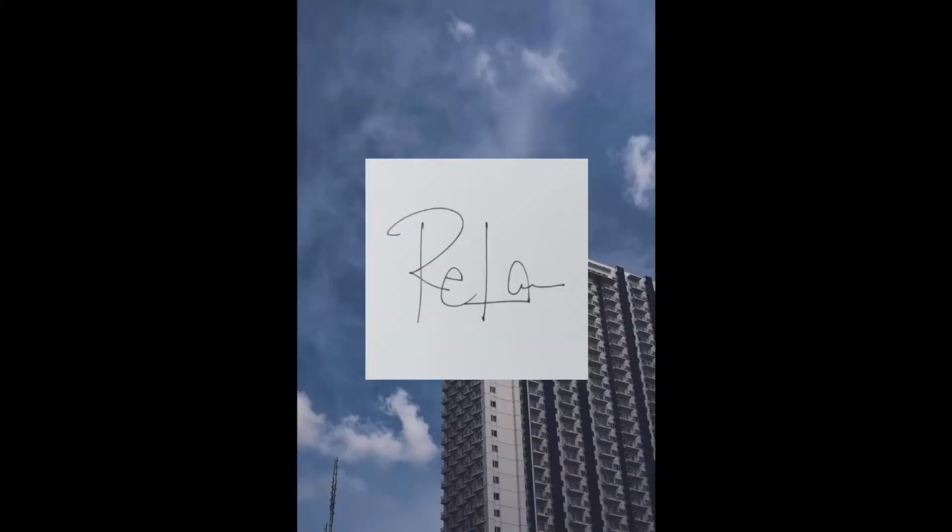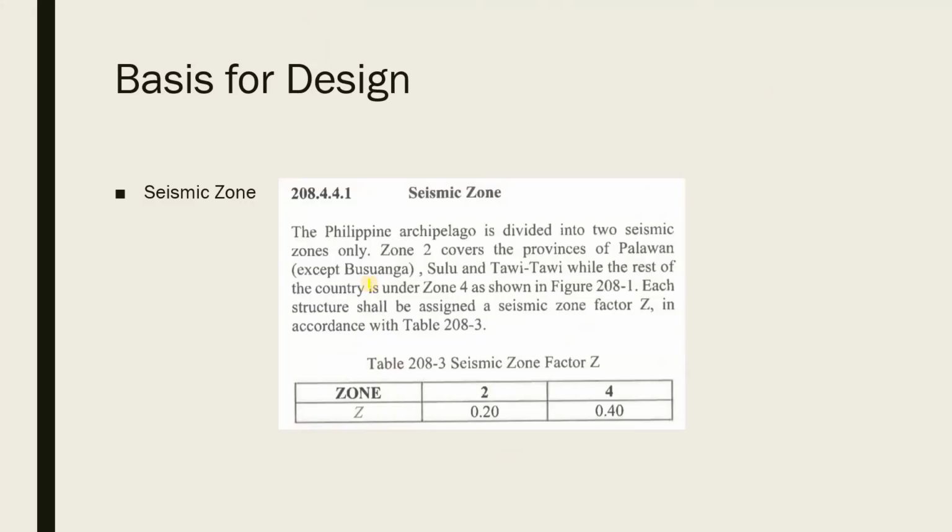Okay, so seismic zone naman. There are two seismic zones sa Philippines. We have the Zone 2 and Zone 4. Sa Zone 2, it covers the province of Palawan except Busuanga, and then Sulu and Tawi-Tawi.